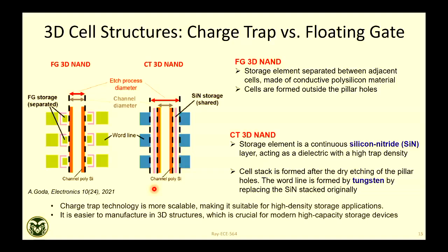Yeah, charge will leave, right? Floating gate means metal or metallic, so that means everywhere the charge will be the same. That means I cannot make this one erased and this one programmed, because program means a lot of electrons and erase means no electrons. If I make them continuous like this, how does it work?